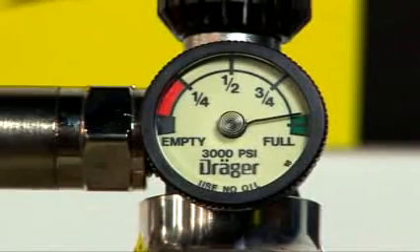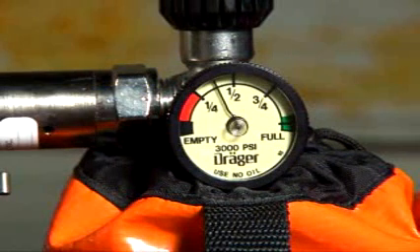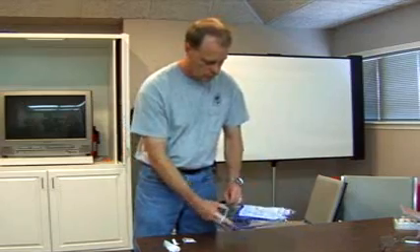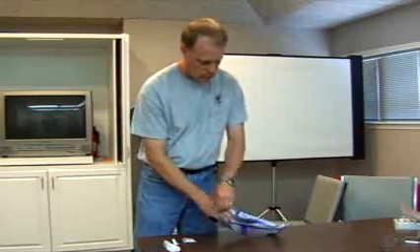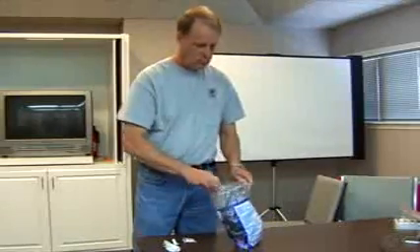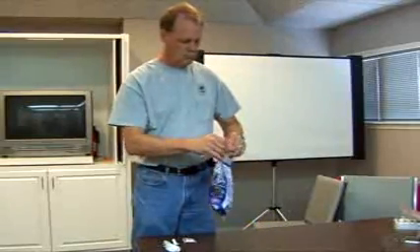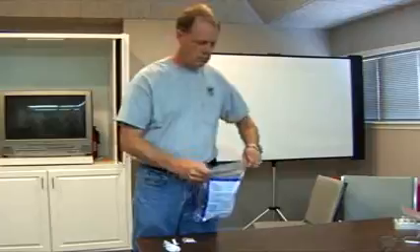Self-contained breathing apparatus, SCBAs, must be inspected monthly. Air and oxygen cylinders must be maintained in a fully charged state and should be recharged when the pressure falls to 90% of the manufacturer's recommended pressure level. Respirators should be stored to protect them from damage, contamination, dust, sunlight, extreme temperatures, excessive moisture, and damaging chemicals. They should also be stored to prevent deformation of the facepiece and exhalation valve.